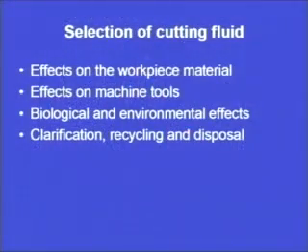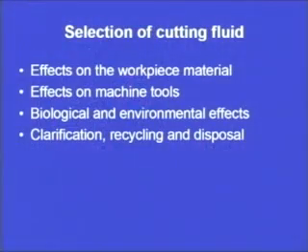Then what are going to be the biological and environmental effects of using the cutting fluid? If at an elevated temperature the cutting fluid reacts with the tool material or the work material, or if some fumes are formed, those fumes may be poisonous in nature. So, all those aspects like the biological and environmental effects have to be taken into account. Similarly, how we are going to carry out the clarification, the recycling, and the disposal of the used cutting fluid also has to be considered before we select a particular category of cutting fluid for performing the intended function of cooling and lubrication in the machining operation.